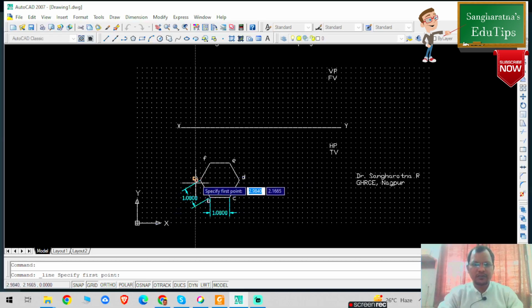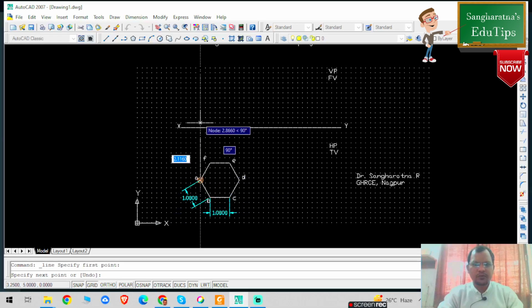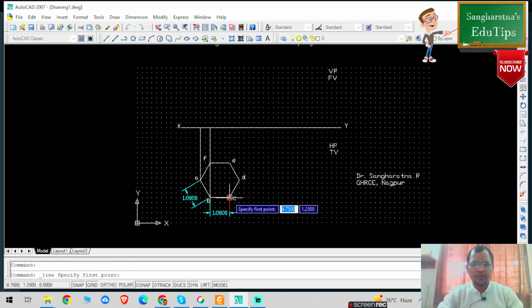And from these particular points I'm going to draw vertical projectors. Okay, so let us say this is my first point. From point D, right, it will pass from point F as well, right? This is my second projector. From point C, this is my third perpendicular projector. Okay, and from point D, this is my fourth perpendicular projector.